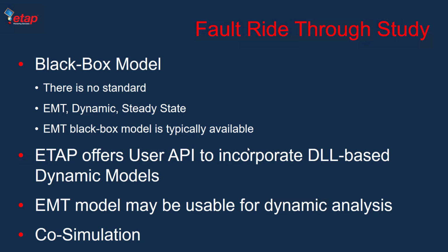Now, ETAP offers a user API as part of ETAP 20 to incorporate DLL-based dynamic models. So basically, we provide a C++ interface for inverters and WTGs, where you can have access to the voltage and powers, and you can inject currents or power back to the system.